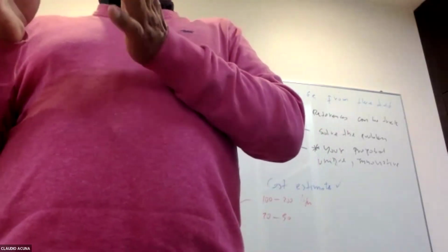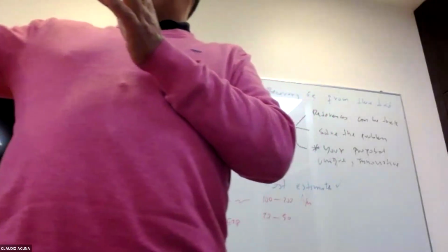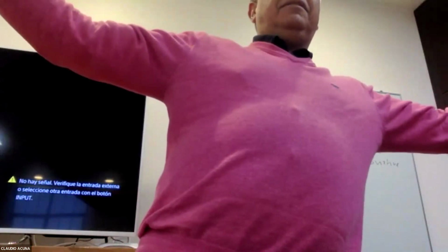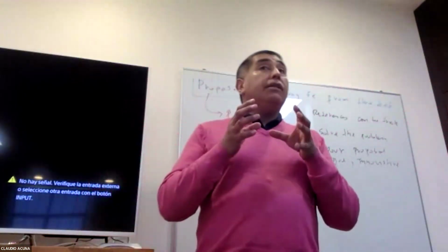Yes, to be conservative, because you don't want to make a mistake with the main equipment. So you're producing that divided by 0.3, you need to put 3 times the feed in the feed material. If you want to produce 1, you need to put inside 3 because you have 30% efficiency. That will give you the size.